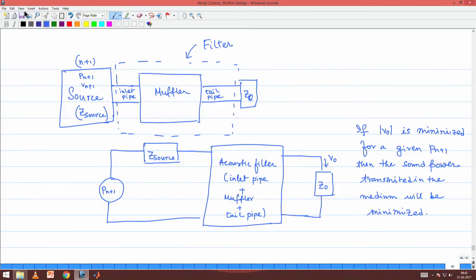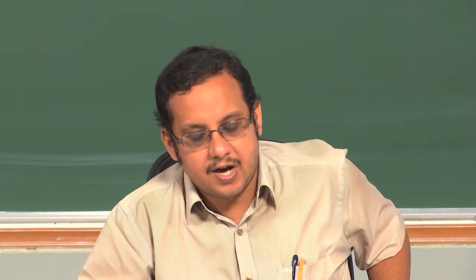This is exactly what is done in electrical circuit theory also, but this approach of designing mufflers, where mufflers are just called acoustic filters, we are just replacing the idea of an LCR circuit with the help of these mufflers, and we are drawing a complete analogy in a step by step fashion, and finally we are led to believe that in order to minimize our sound transmission into the atmosphere, we should be able to have a certain design objective, and that design objective comes out neatly to be having some shunt path.